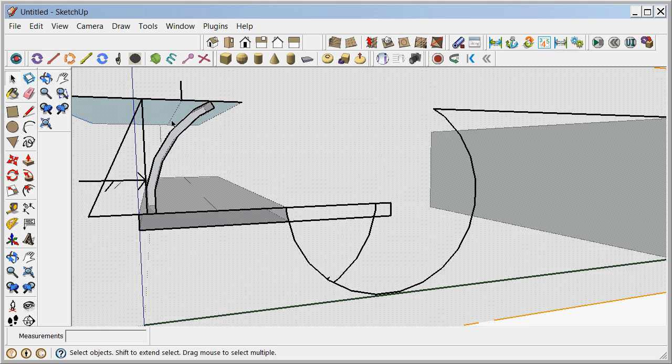And so by adding those three up and then using a little geometry, you can determine exactly where the center of pressure is through here, because you'll know their direction, and the direction has to go through the center of the circle. So that's probably best done graphically in a 2D world where you draw the cross section, you draw up each of these resultants, and then you use the mass prop or some other way to get essentially the centroid of more or less the outside of a fillet here. So there are tables for that, but you can't beat mass prop to get the centroid of a shape.